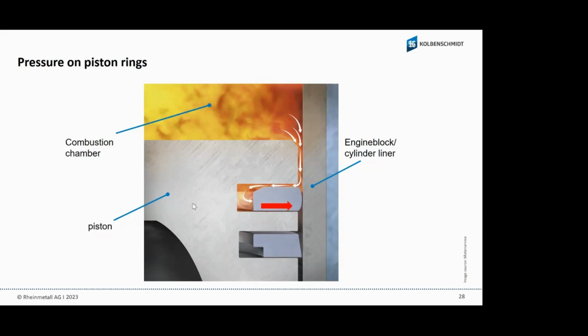You go with a truck or a car down the hill, you release the gas pedal, and then the combustion pressure decreases. The tension of the piston ring also decreases, and then you have blue smoke. When you go with this car and climb up the hill, the combustion pressure increases, also the pressure behind the piston ring, more tension between piston ring and oil and the surface of the cylinder bore, and a better sealing effect, and no blue smoke.